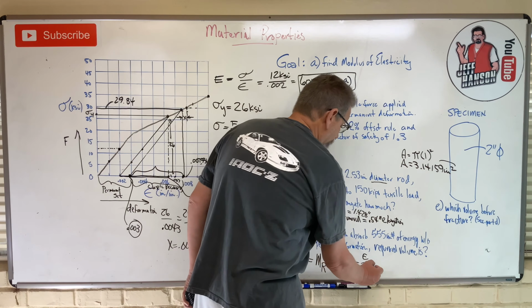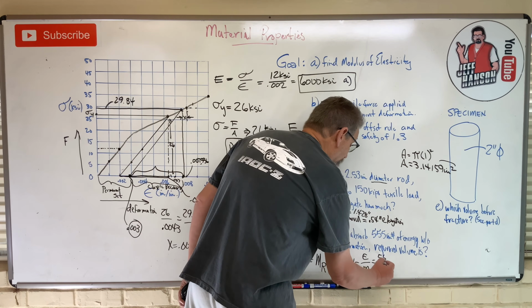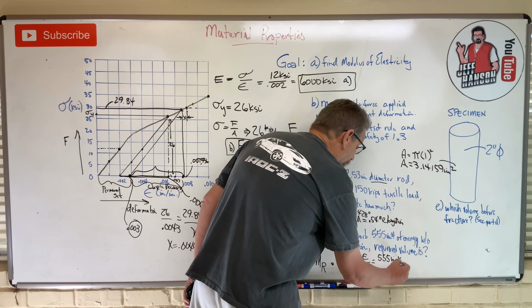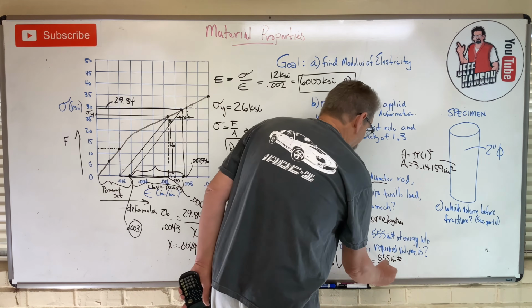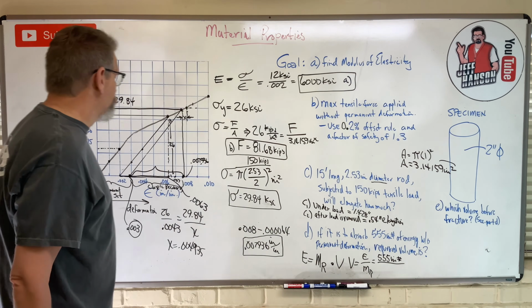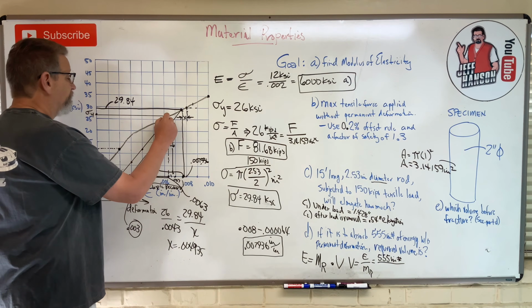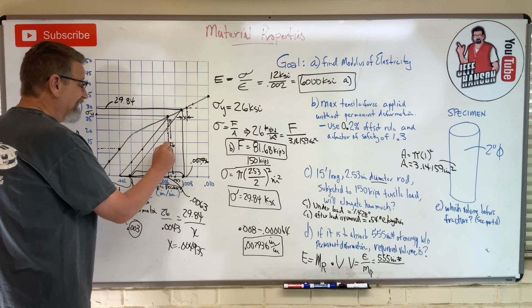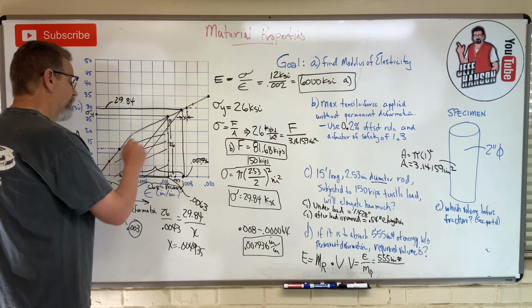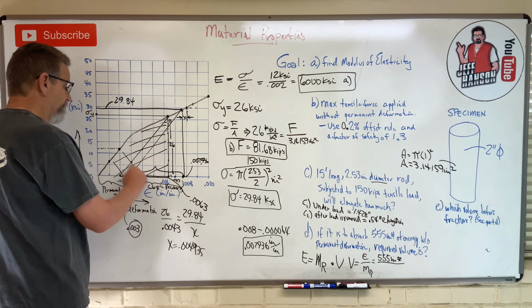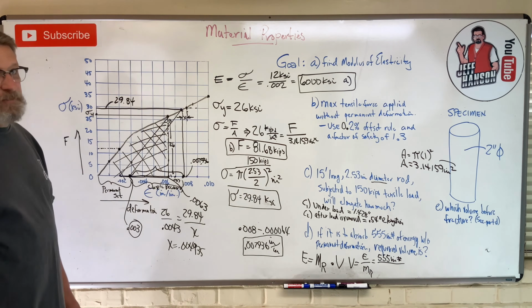And that's going to be this, okay? The volume is going to be 555 inch-pounds. Don't screw up your units here, okay? Divided by the modulus of resilience. The modulus of resilience is, take the yield stress, drop a line straight down, and the modulus of resilience is this whole area underneath the curve, okay? This area here. We're just going to consider that to be a triangle.